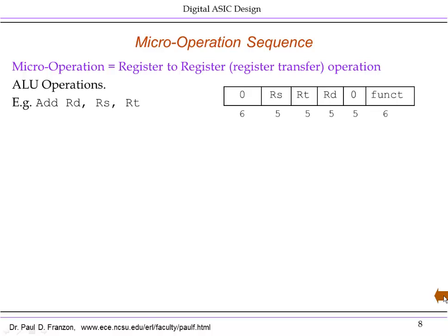So the next step is to take our algorithmic intent, in this case the specifications of the instructions, and work out in detail what has to happen on a data path, which will eventually be a modified version of the previous page. And again, though here I'm dealing with an instruction set processor, these steps can be applied to any design. We actually did this in the motion estimator. There was only really one type of microoperation that mattered. So it was relatively simple.